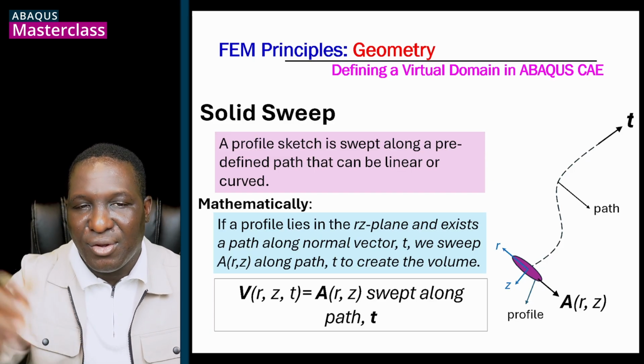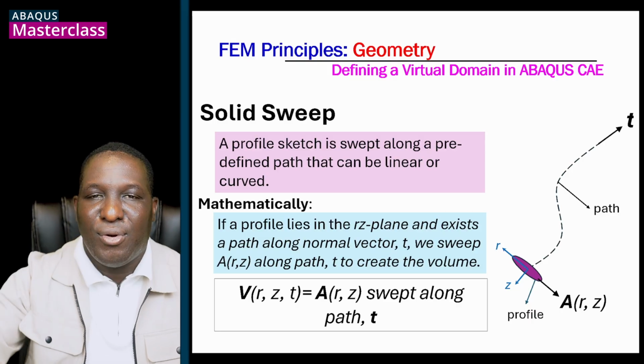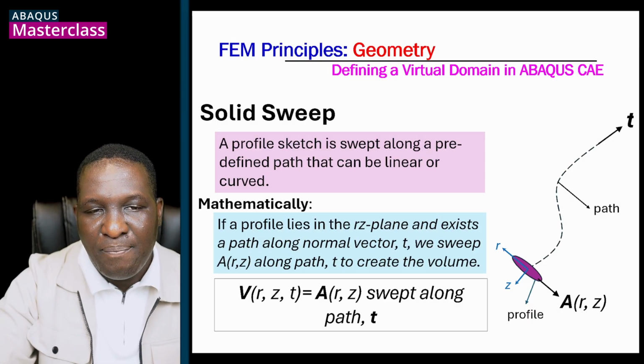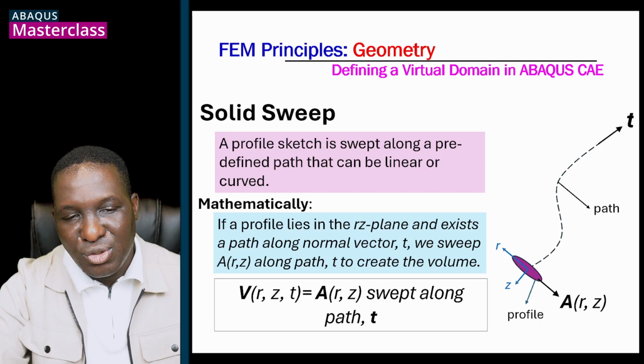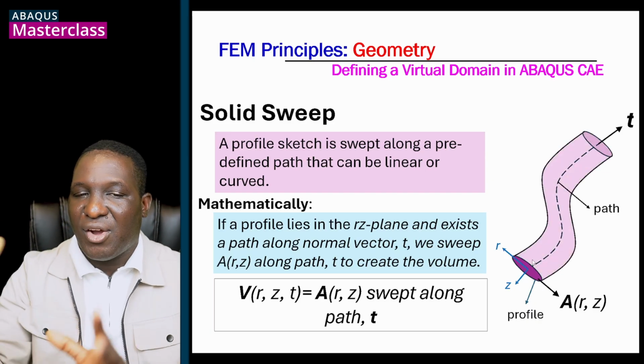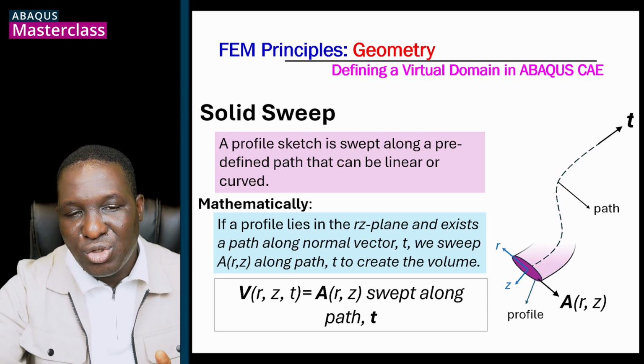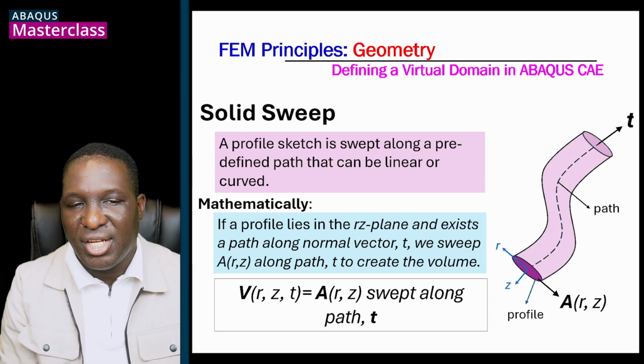So I've used a nonlinear path in this case, where the outward acting normal is tracking every point along this path. And then at the end, what you're going to do is extrude this base, or sweep this base, in this way to now create the geometry that we're interested in. So if we do that again, you extrude that base to create the geometry that we're looking at.